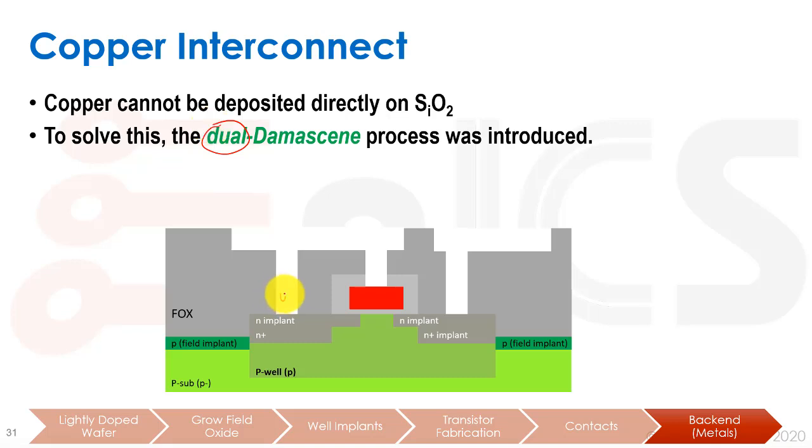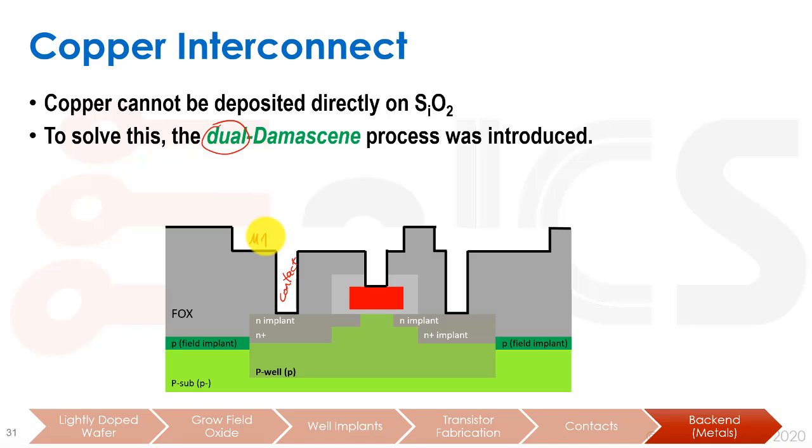So this is our contact layer. This is already our metal 1. So we already etched away, with a separate photolithographic process, our metal 1. We haven't put in our liner yet, and we haven't filled our plugs yet. Now we are going to fill it with our liner. So the liner is going to both line the contacts, but it's also going to line the metal 1 areas.